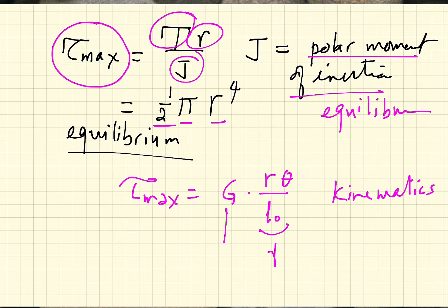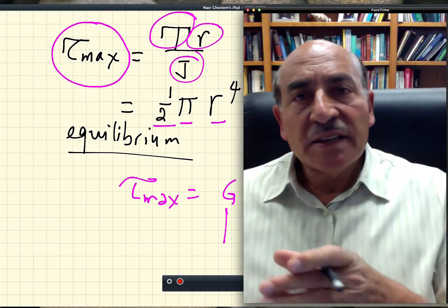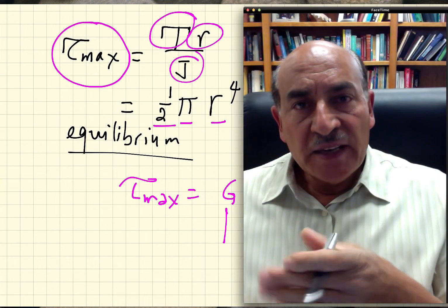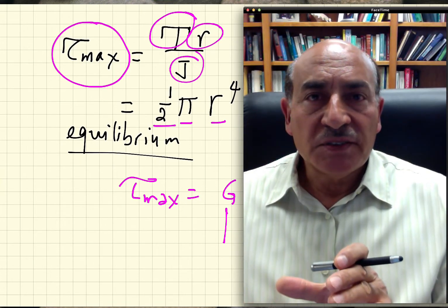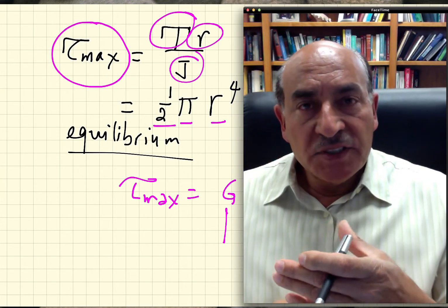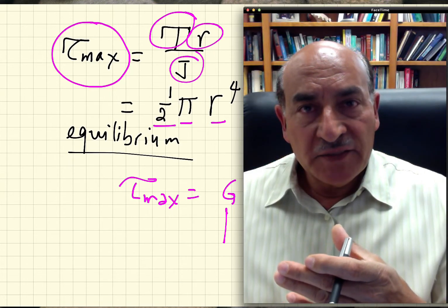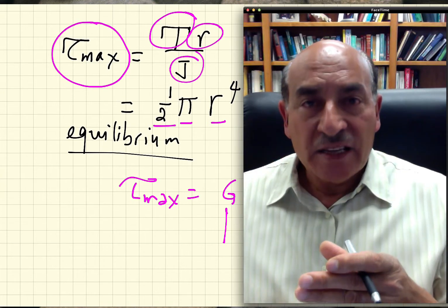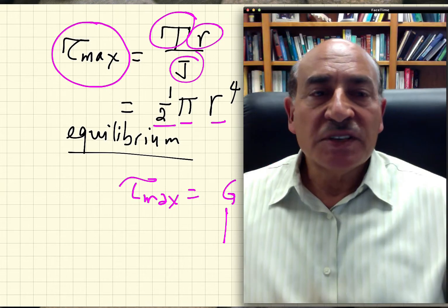They should give me the same value of the maximum applied shear. Now the question is, if I take a bar and I torque it initially and let go, then it will go back to the original shape. If I exceed a certain point, then the bar will go into plastic deformation, and if I let go, it will just go back a little bit, not the entire range. Very similar to the case of tension tests.